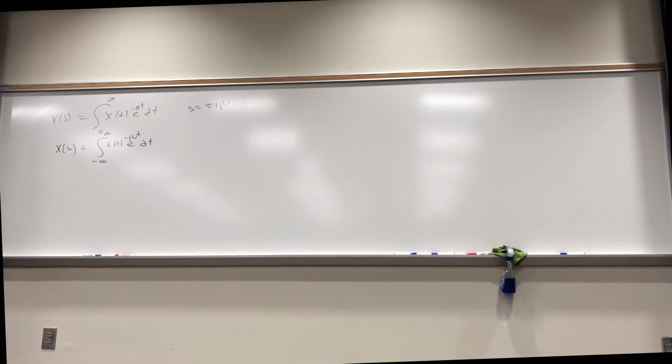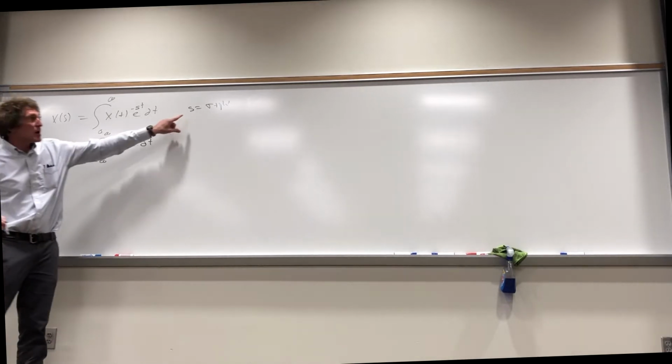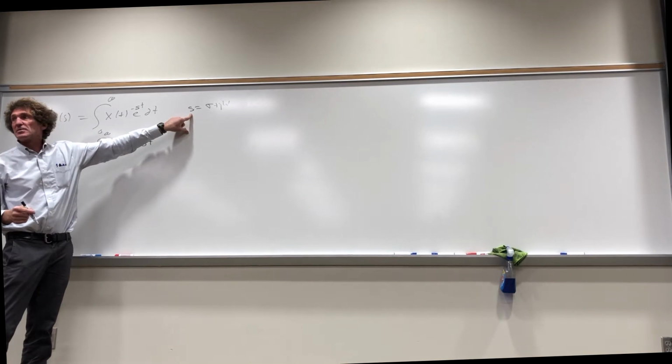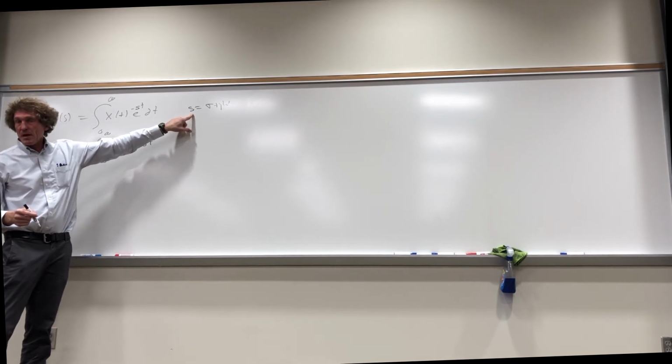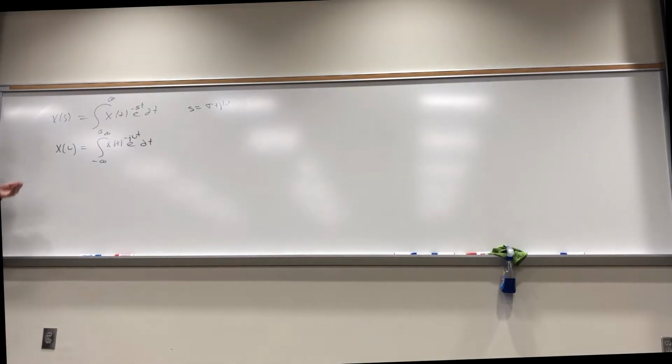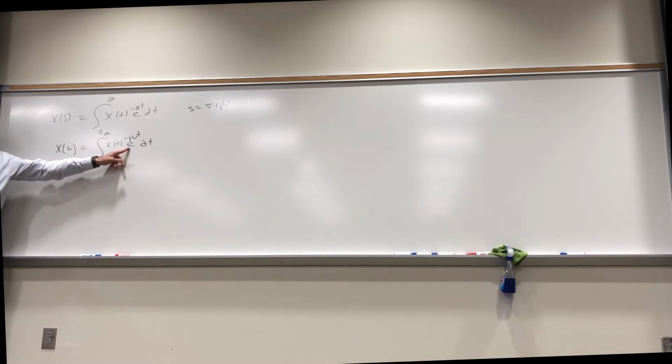Now, when you look at that, the reason we talk about complex frequency is we can find stability information, right? If we look in the complex plane because of that. This is really something where both of these are analyzing a waveform. They're not synthesizing it. Now, the big difference is Fourier starts from minus infinity, and it has e^(-j omega t).